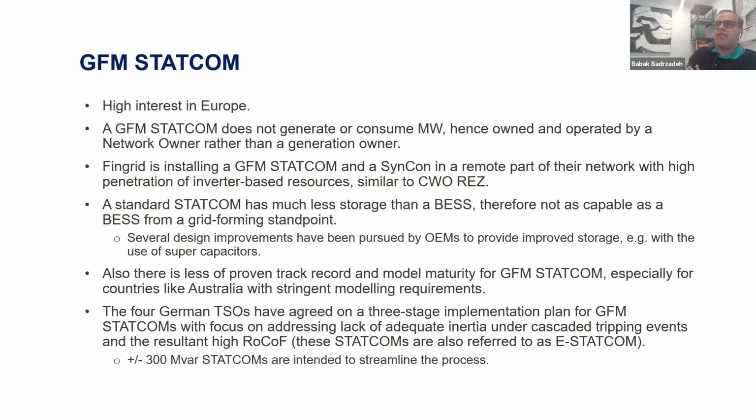So why are people considering grid forming STATCOMs then? One advantage is that because of the regulatory requirements that are in place pretty much across the Western world, the utility or transmission or independent system operator cannot own a device that generates or consumes megawatts. Whereas with the STATCOM, that problem is rectified, because obviously it has nothing to do with megawatts, and it can be owned and operated by a network owner.